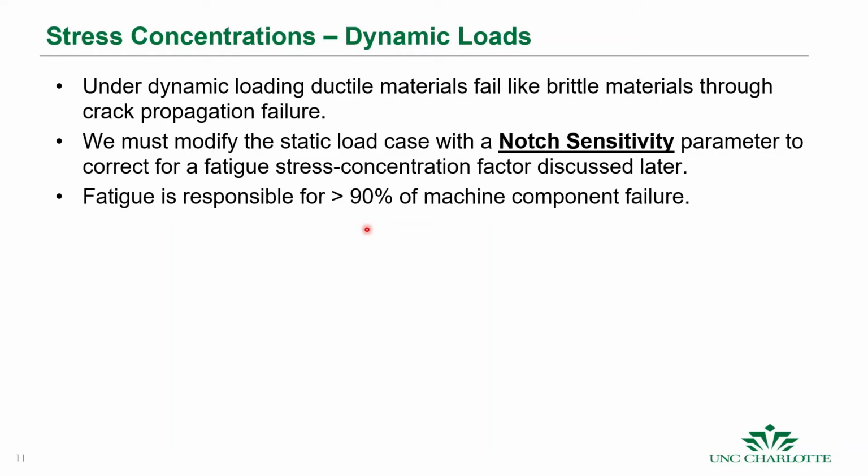Now, what we've discussed is only for the static case. Under dynamic loading, even ductile materials will fail like brittle materials through crack propagation failure and fatigue failure, which we'll talk a lot about. Okay, so we have to modify these static load cases and stress concentration factors using the notch sensitivity parameter of that condition to correct for a fatigue stress concentration factor.